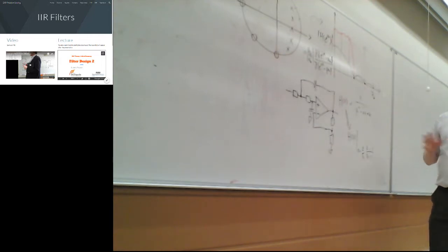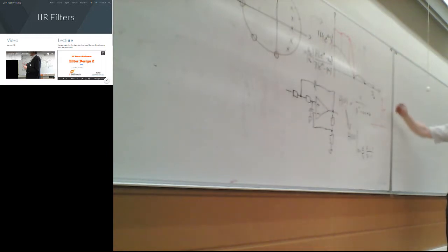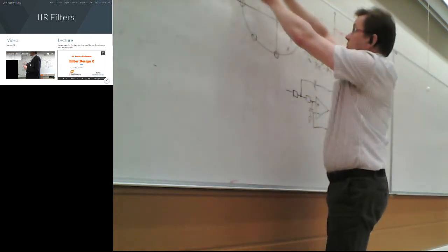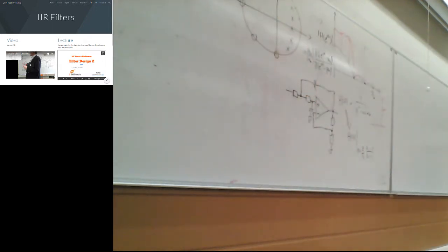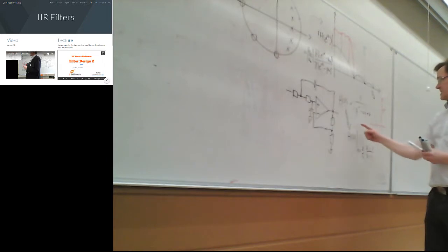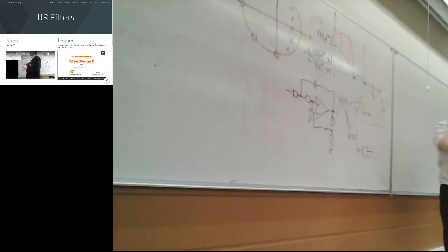But with a distortion. It's kind of a violent operation, since it basically takes the plus and minus infinity of the frequency axis of the S plane, where you have j omega here, and turns it into the unit circle. So that's what the transformation actually does. It means that it's really doing some serious distortion of the frequency space.